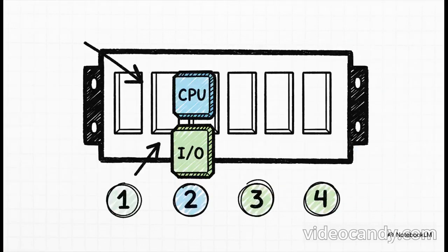Okay, so when you open up Logix Emulate, you'll see this empty virtual chassis. We're going to start by adding our main components. In slot 2, we'll create our virtual controller. That's the CPU. Then, right next to it in slot 3, we'll add a virtual input-output module. And believe it or not, with just those 2 clicks, our virtual hardware is pretty much built.